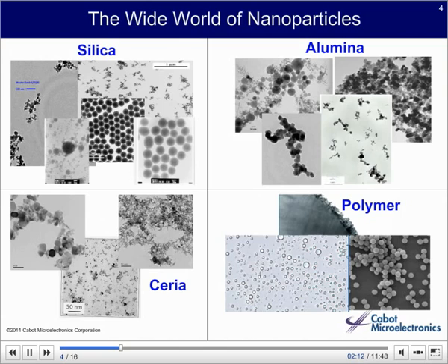Silica can also be crystalline like quartz or fractal like a snowflake when produced as a fume from burning silanes such as tetrachlorosilane or methyl trichlorosilane. Most of our early products employed fumed silica and fumed alumina, but now we are using a wider range of engineered nanoparticles to improve cost, quality, and performance. Depending on how and where the silica is made and from what raw materials, it can make a big difference in how it performs in a slurry. And that's just silica. The same things can be said for virtually every nanoparticle.